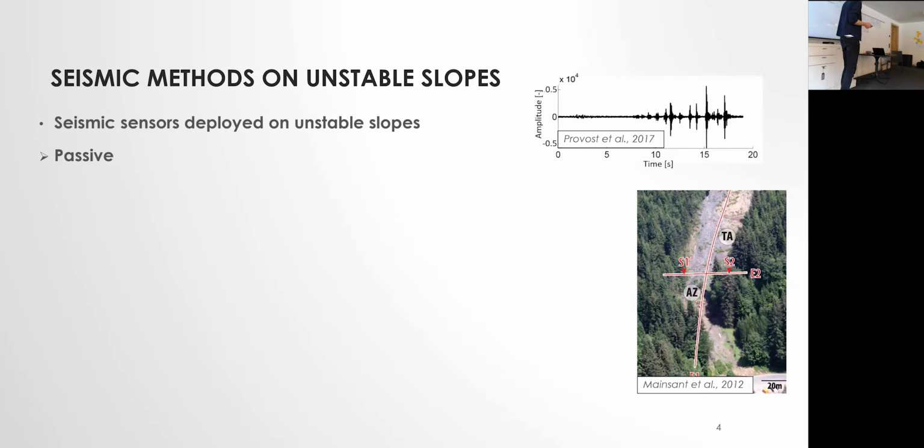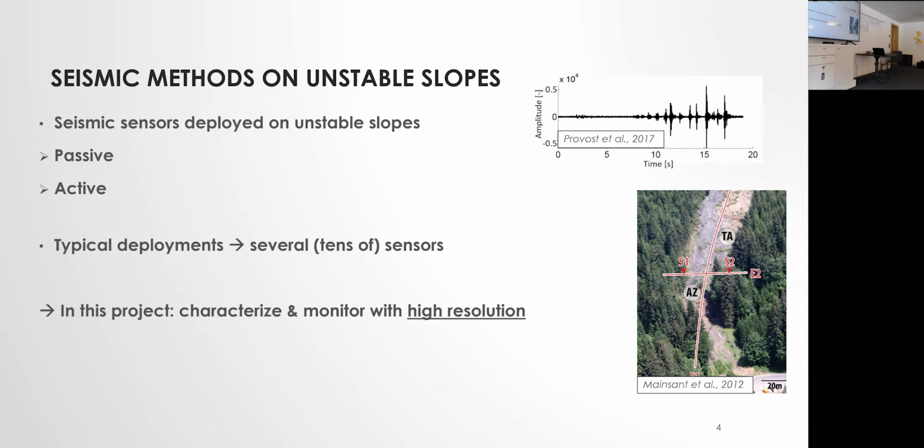Now, typical deployments of such seismic investigations often consisted of several tens of sensors, and that is the main difference with our project, where we try to characterize and monitor such a very large-scale landslide with very high resolution in a 3D sense. And we try to do that by employing more than 1,000 autonomous geophones or nodes, and by using fiber optic techniques such as distributed acoustic and strain sensing.